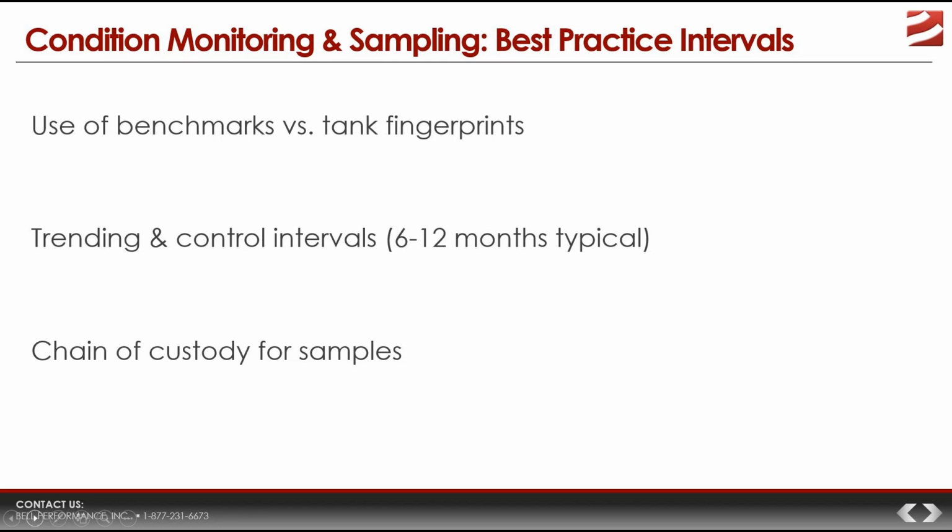Now, we've been trying to stress that every tank is different. However, if you want to generalize this situation, then a common control interval for bulk storage fuel tanks is about 6 to 12 months.